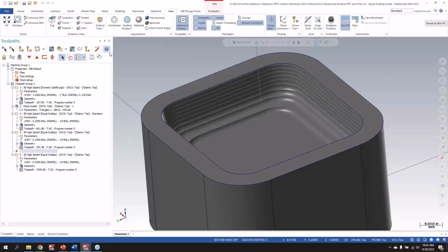Especially if you're running smaller finishing tools, you don't want it to get into a scenario where maybe I'm only finishing a little bit of material on the wall, but then once it gets to the corner, even though I have a really small step over, that tool is engaged on 2 or 3 of the sides of the tool, as opposed to being like a traditional shoulder type cut, where depending on my speeds and feeds, I would overload the tool and break it, or get a worse finish, and so forth.